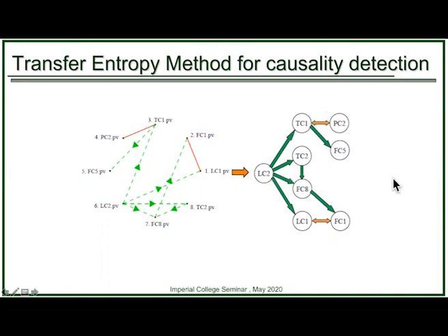And in fact, this was confirmed by Eastman engineers that yes, it was the level control loop 2, which was the cause of oscillation. There was a sticky valve in this level loop, which resulted in limit cycles, which then propagated to all of these other loops.